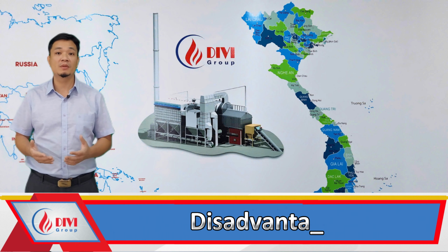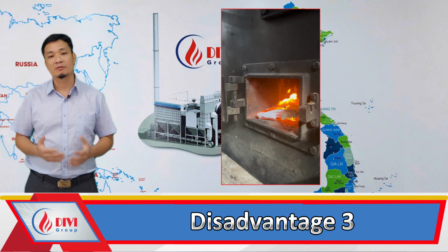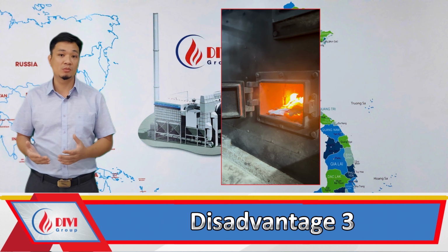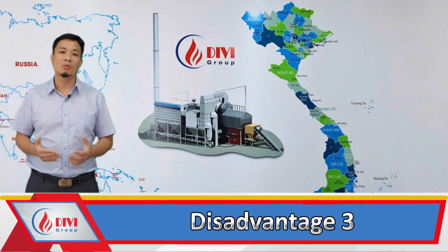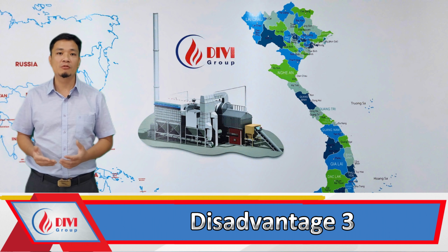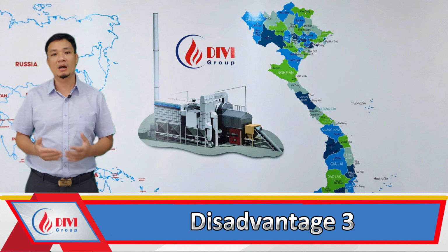Disadvantage 3. During boiler startup, a significant amount of energy is required to heat the fluidized bed material that forms the fireball inside the combustion chamber, leading to longer startup times and increased fuel usage during ignition. For factories that do not run boilers continuously, 24/7, the startup costs of fluidized bed boilers with a fluidized bed material are significantly higher compared to those without a fluidized bed.